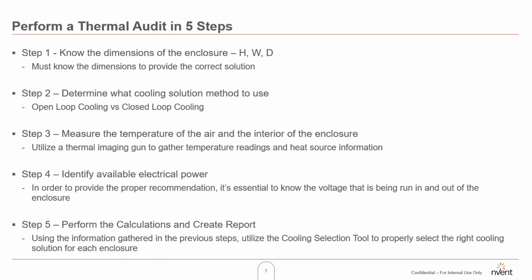I do like to take pictures of any existing ACs as well. It can be very helpful when creating the report. You can cross-check the current cooling solution and see if the BTU matches correctly to your calculation. Sometimes ACs are undersized, and that just happened to be what was in stock. Could lead to failures down the line, just something to keep in mind.